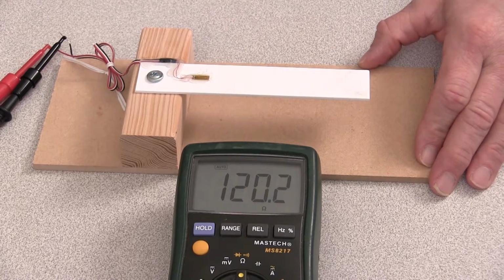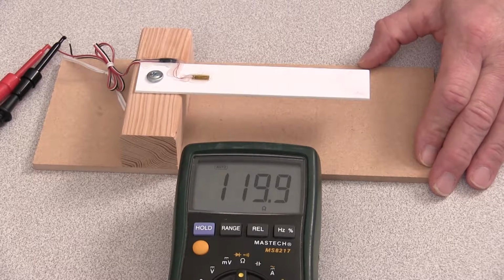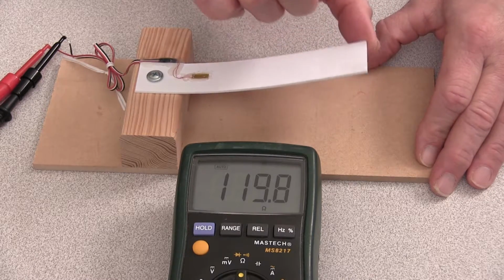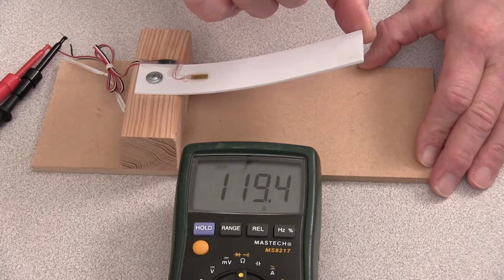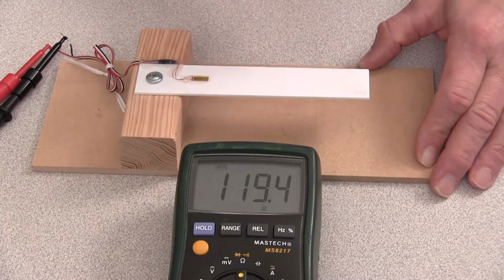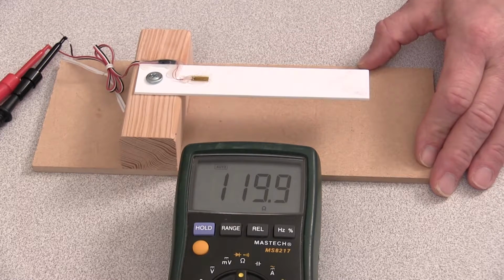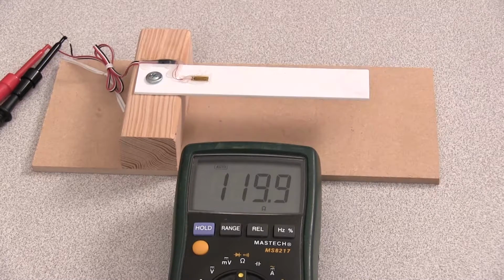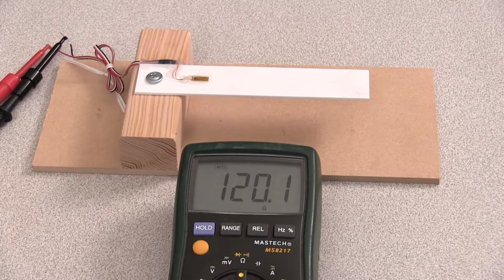That gives me 2 points that I can use to estimate a straight line, but for future reference, I'll get a third data point by raising the tip of the beam. Since positive is down, the deflection at this point will be about negative 6 centimeters. At this deflection, the resistance of the gauge is about 119.2 ohms. Now let's use the first 2 data points to estimate the equation of a straight line and then see how well that line predicts the resistance at the third data point.